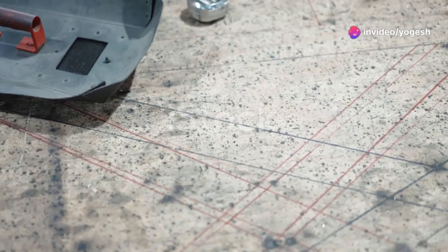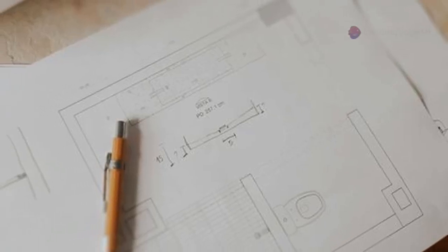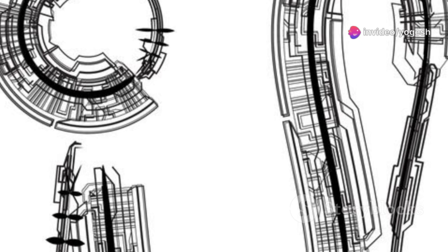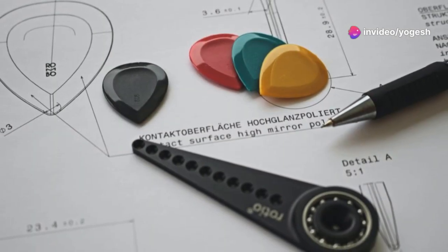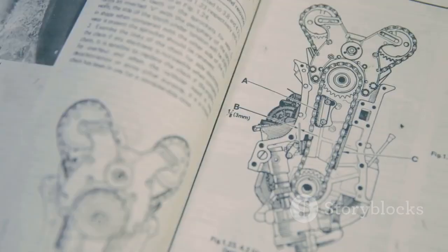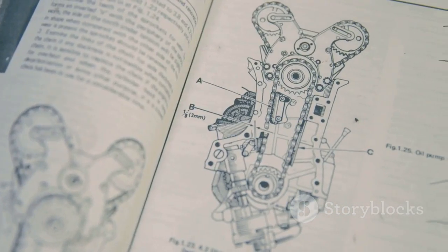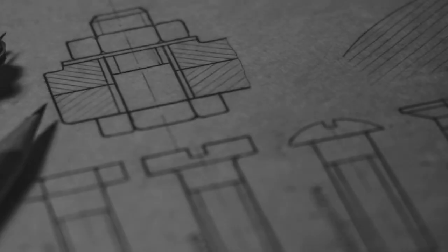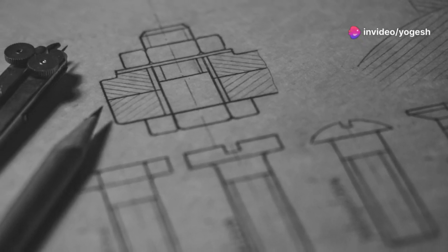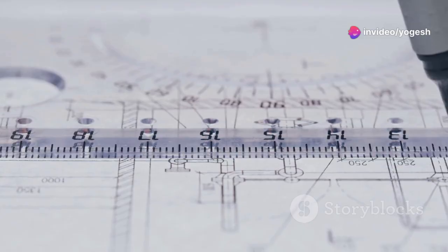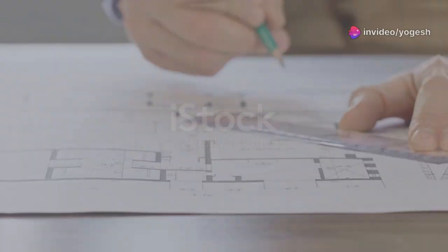Phantom lines show alternate positions, motion paths, or related parts. Think what-if scenarios. They're thin, with a long dash and 2 short dashes. Use them to show a lid's open position or a bolt's mating parts, without cluttering your drawing. Phantom lines communicate movement and context efficiently. Use them sparingly, only for critical, immediate relationships. Too many phantom lines can overwhelm the drawing.